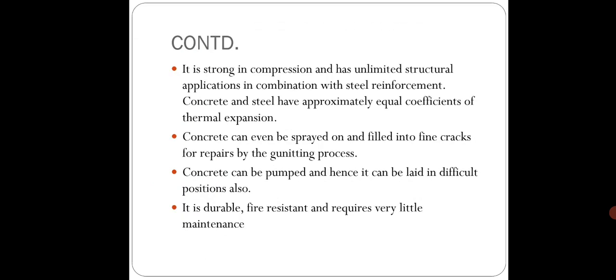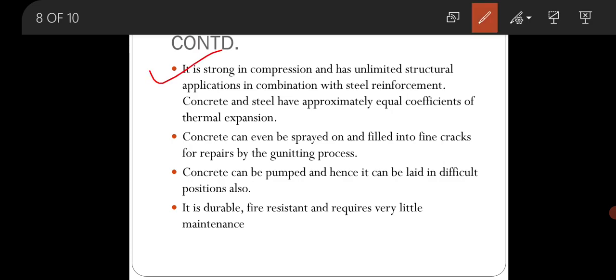Next advantage is it is strong in compression. Also it has unlimited structural application in combination with steel, because concrete and steel have nearly equal coefficient of thermal expansion. Next advantage is it can be spread and applied into fine cracks by the process of gunniting.